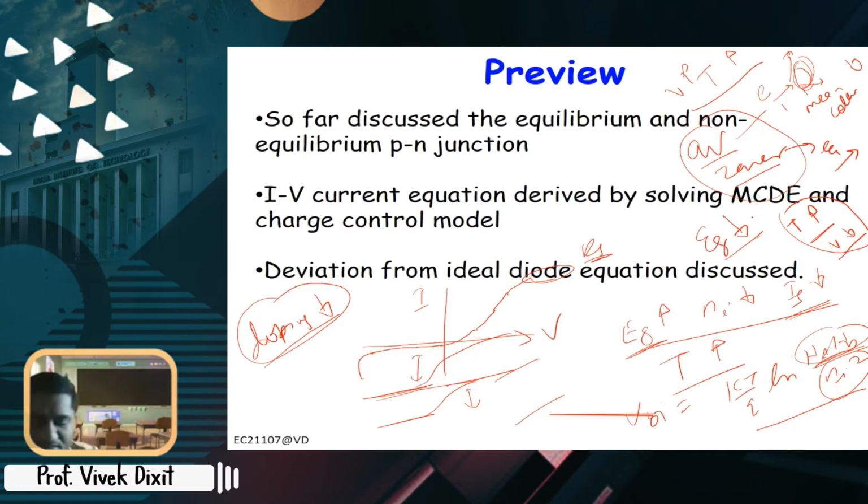Okay, so what point was I telling you here? For avalanche breakdown, the breakdown voltage depends on, let's say this is a highly doped P plus, and this is the N region. So this avalanche breakdown depends on which doping, P plus doping or N doping? We discussed this in the last class. It depends on the N doping, the smaller doped side, right? It's inversely proportional, 1 by ND. So if you increase this doping, what will happen to the breakdown voltage? It will reduce, right? So if you want high breakdown voltage, you will have to reduce the doping.